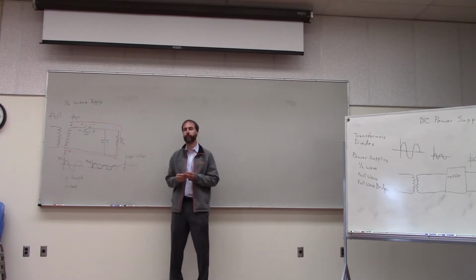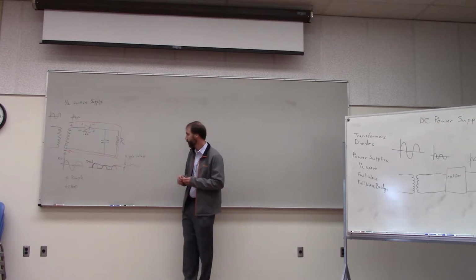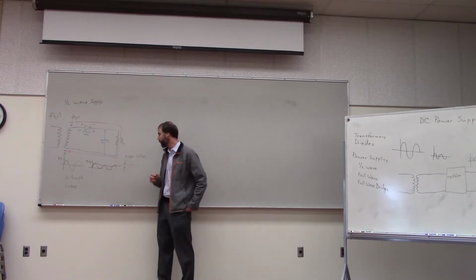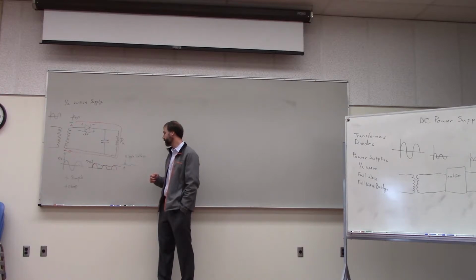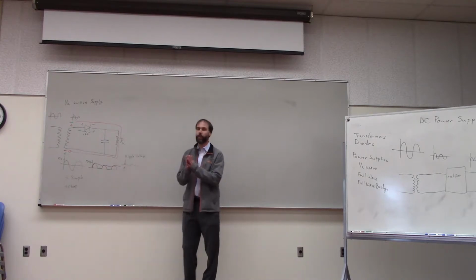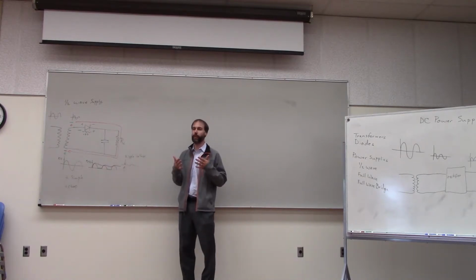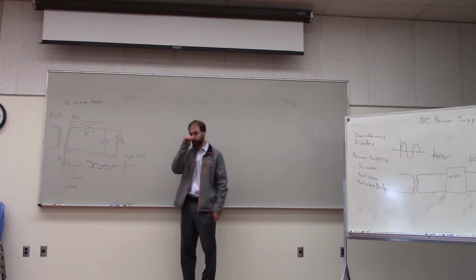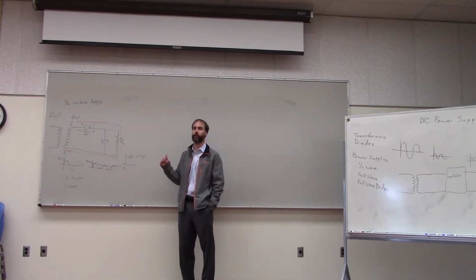How would you determine the size of the capacitor that you want, like the voltage? Is there an equation? There's not really an equation, but it's something that you would look at in your design. So you would look at the other components in your circuit, and you might be able to tell how much of a change in the supply voltage they could tolerate.